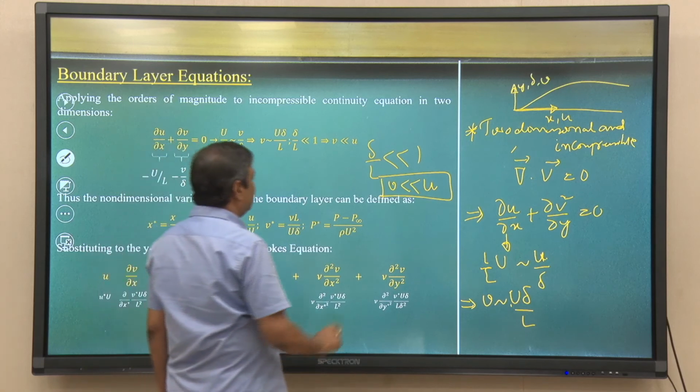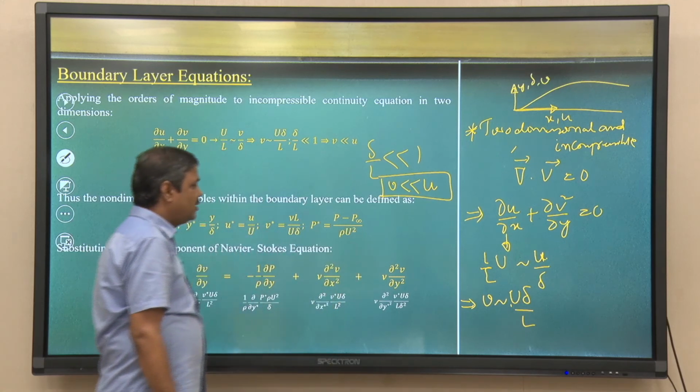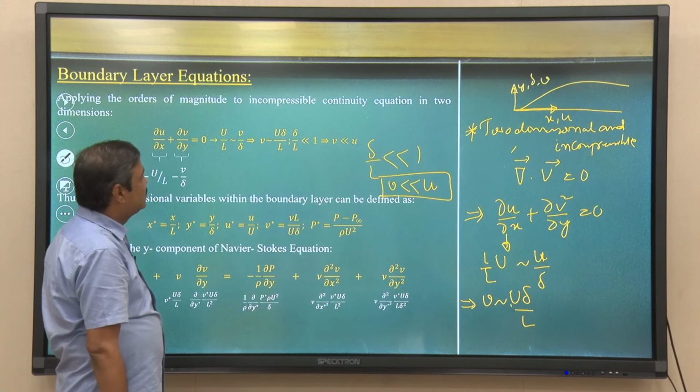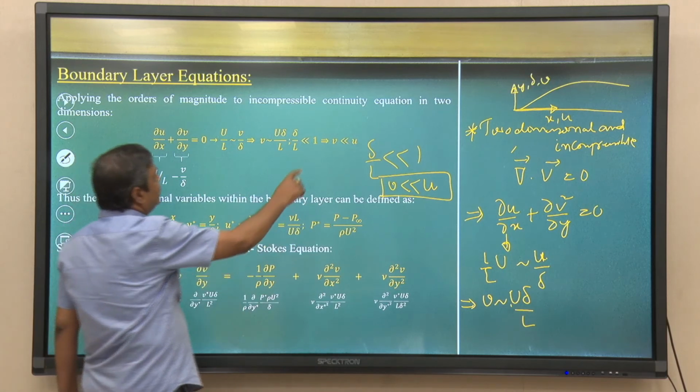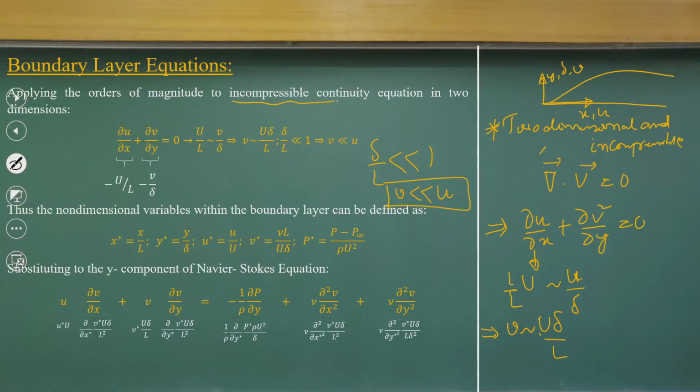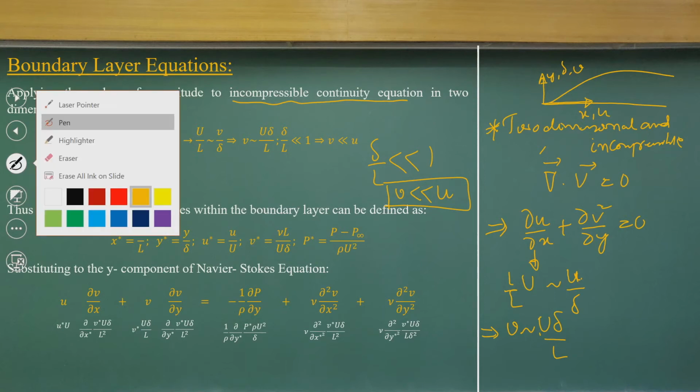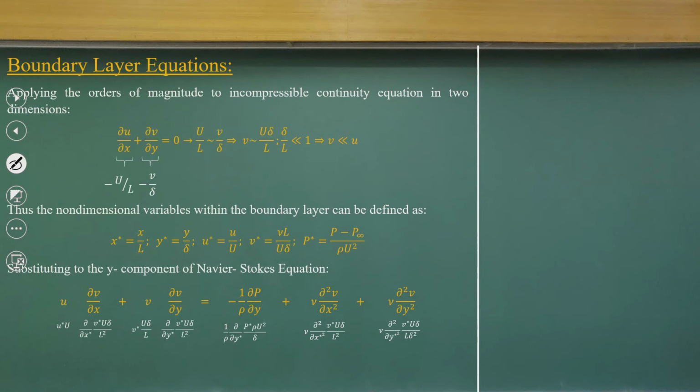That is the order analysis. That is what order analysis gives by just analyzing the incompressible continuity equation. Now, if I go to the next level to find the order of the other components, that is what the approximations look at. As I said, in non-dimensional form,